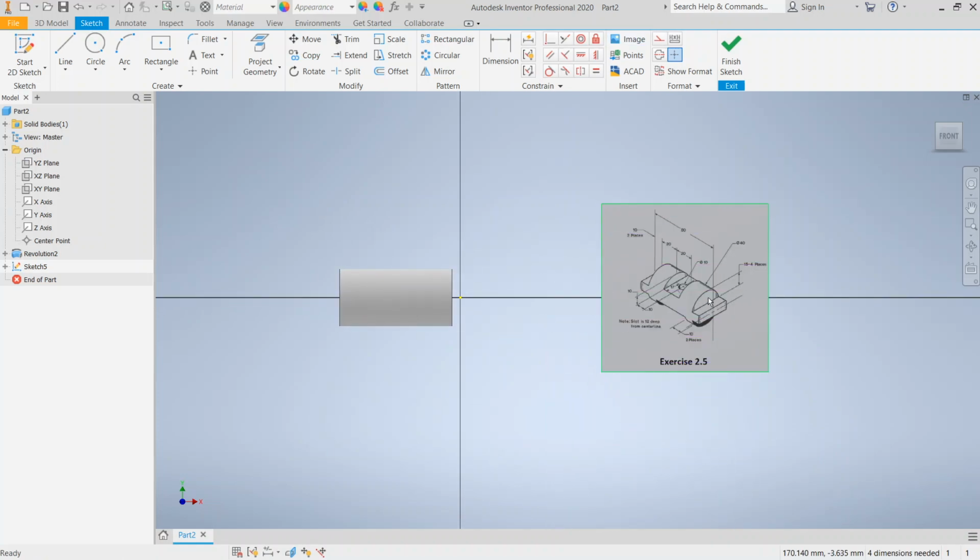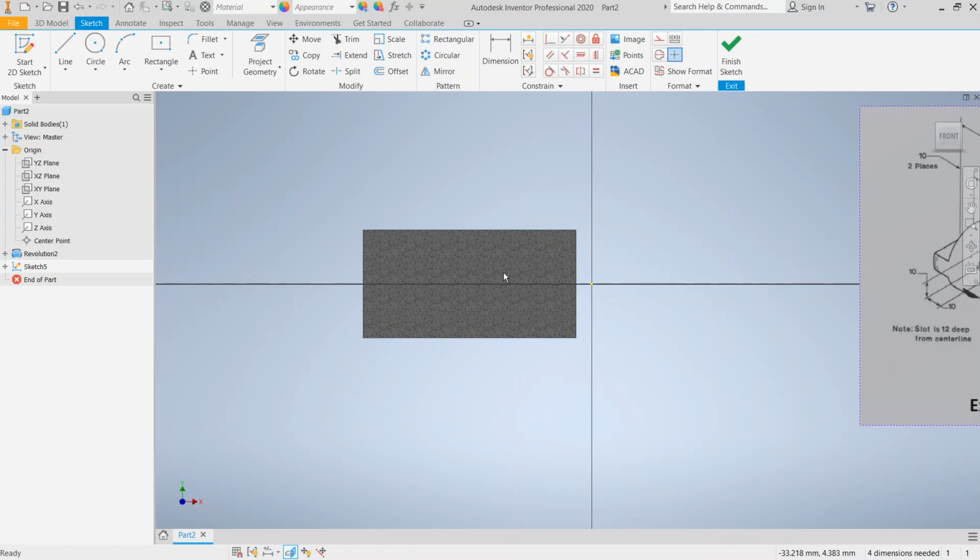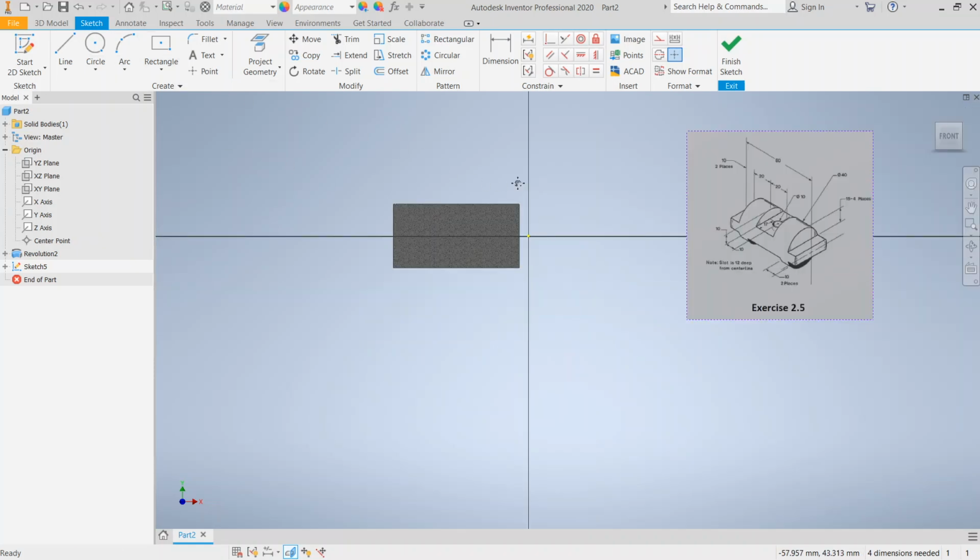So I want to create these cutouts. There's 4 of them. It seems like they are all equal. So I'll just press F7 to slice the grid, meaning I'm removing the other half. Like, you're not removing it permanently, you're just removing it temporarily.